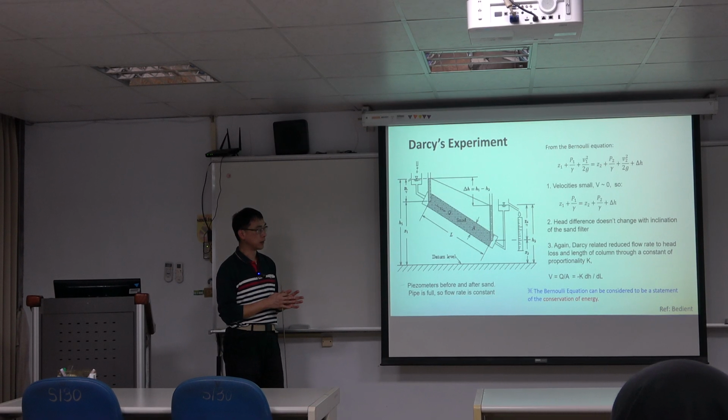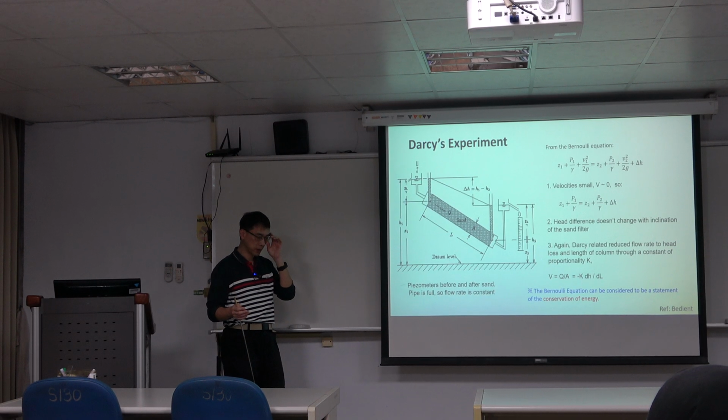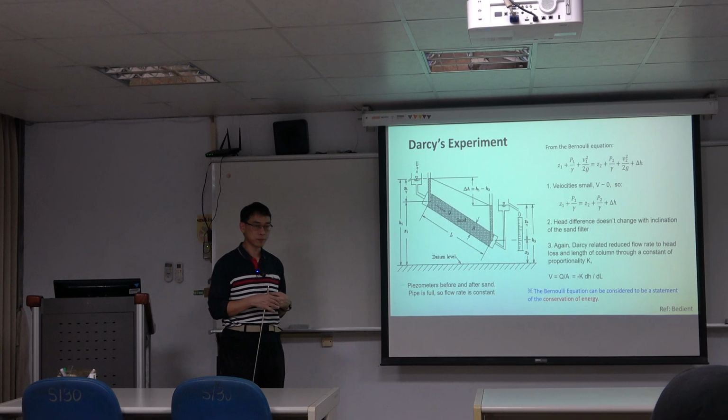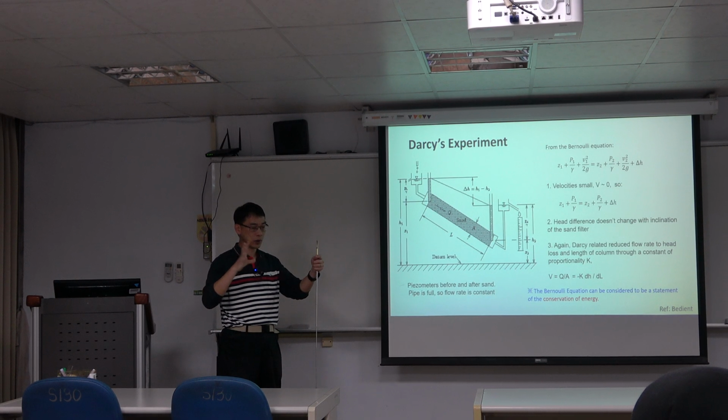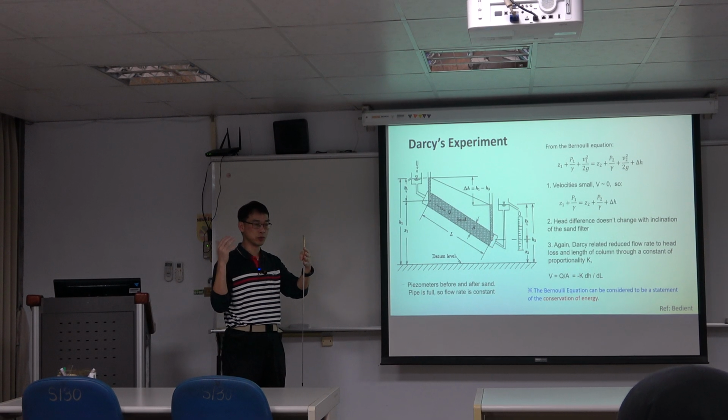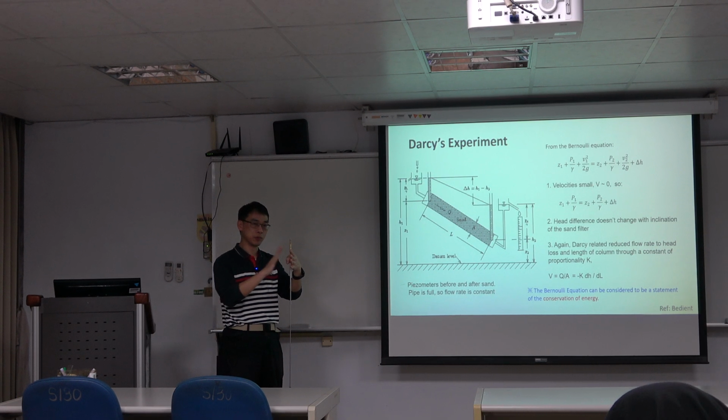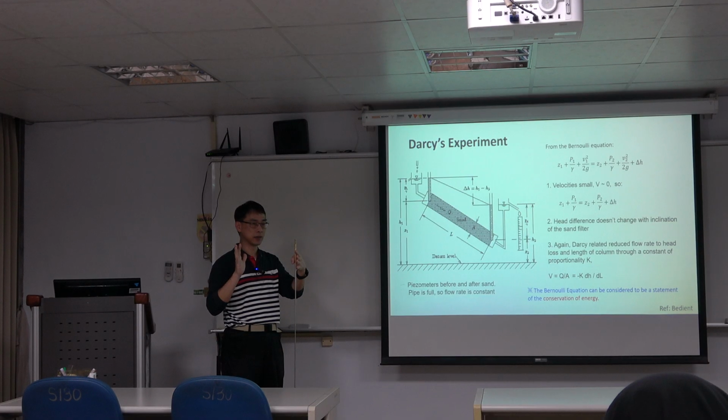Steady state means that the outflow equals the inflow. Remember that when we talk about steady state, the outflow equals the inflow, so we do not have the storage effect. Storage is a kind of lag concept. For example, if you have 1 unit of flow in and 1 unit of flow out, the flow just goes directly through without changes, although it is the water inside that pushes the water out, not exactly the same particle moving. So you have the same unit in and out, and it becomes a steady state.